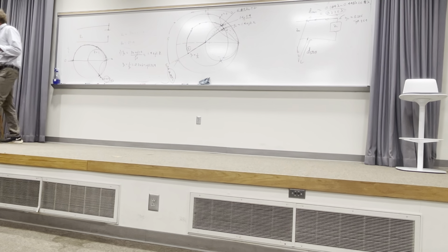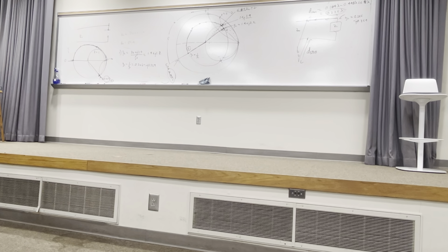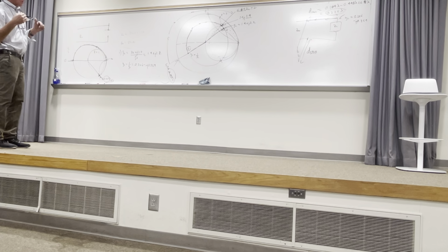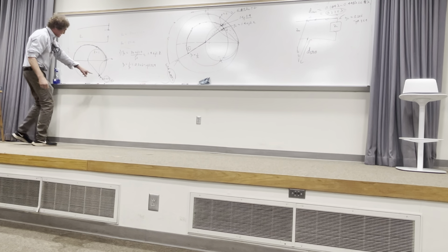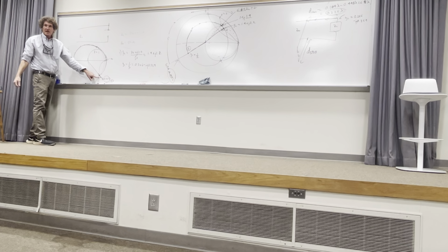All right, then I'm going to see if it's a Smith chart problem. 0.315 is on the R=1 circle. That's the location of the 1 minus JX on the R=1 circle. No, I don't care about that. I care about this. I want to know just the J. That's 0.325 if you go off the R=1 circle.